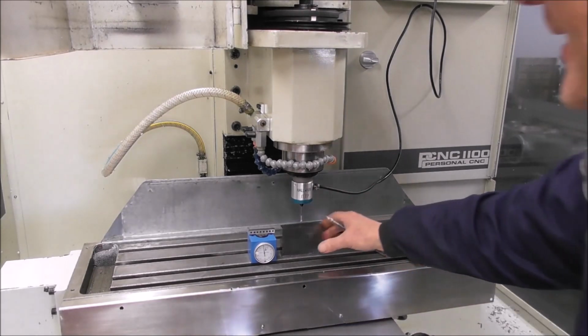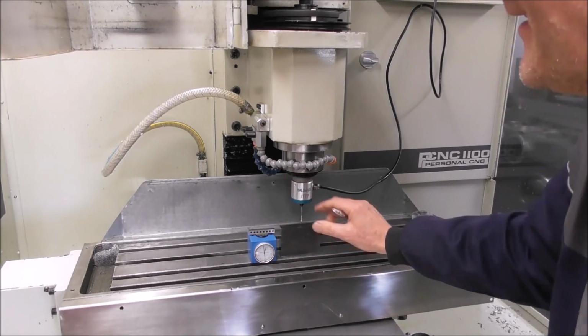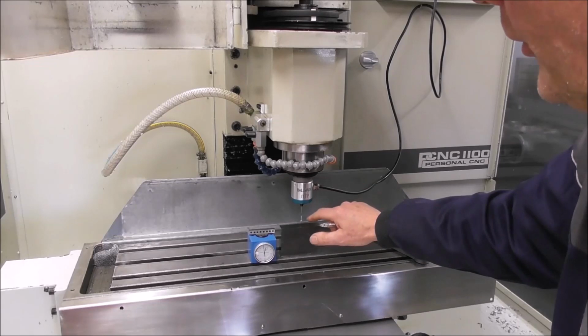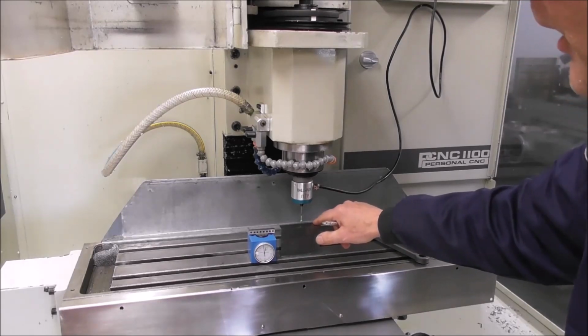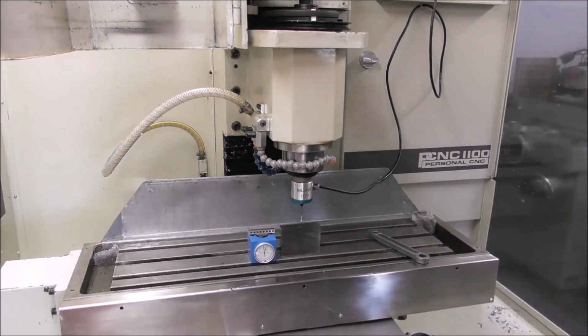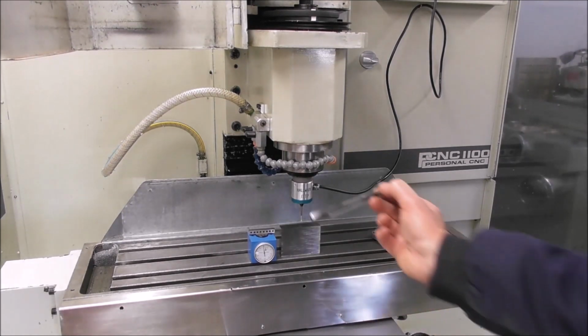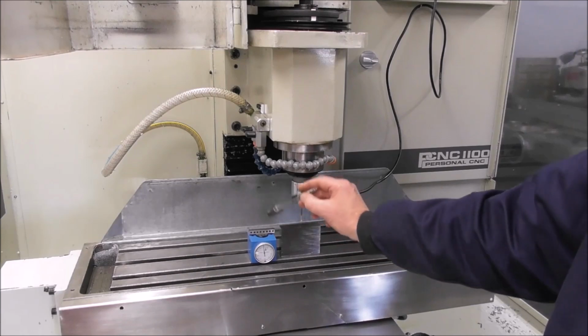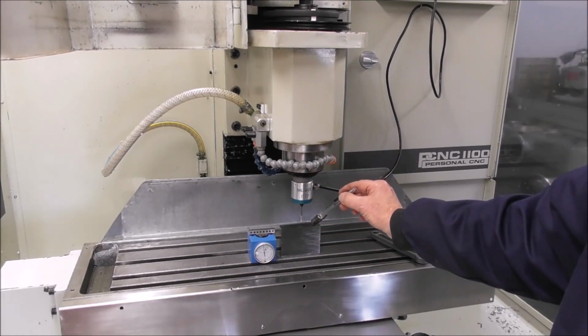So let's say this is our work. Let's say we've clamped it or we've put it in a vise, and we want to set all the tools to the same surface, the top surface, for example, of our work. Then we just put a probe in, set it on tool number 99, probe Z, set work origin. Now we have got all of the tool lengths which we've measured relating to the top surface of the work.